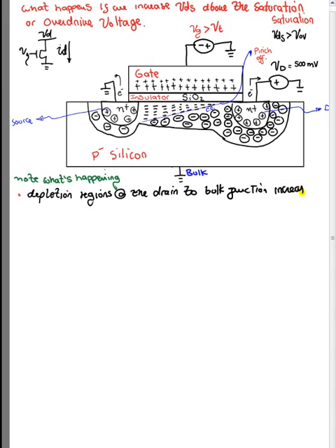And we know that from previous cases because now we are biasing the drain harder, right? We're putting a greater voltage through there. Meaning all these extra electrons, more and more, are actually going out, right? Which are uncovering these fixed charges, which increase the amount of depletion region, make it wider.